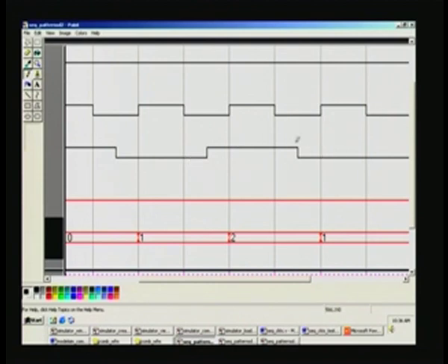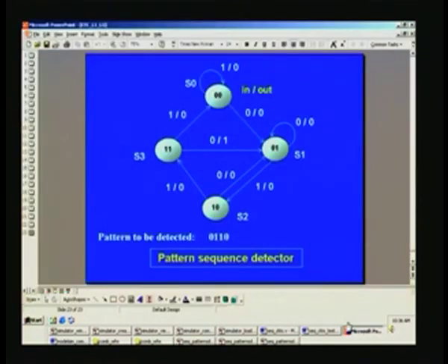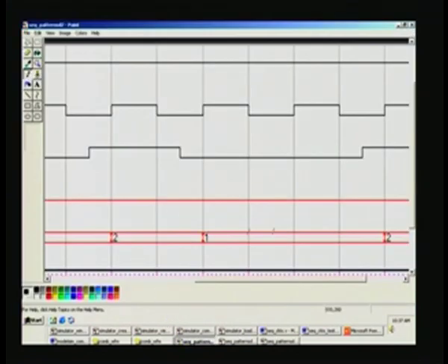So, naturally we will continue to remain in the same state, as per this. So long as it is 0, it was 0 there, and it went to state S1 and then continues to be in S1 so long as 0 is the input, and the corresponding outputs are all this here. What is indicated as out in the waveform is precisely this, and in is this. So we continue to be here in S1 state, that is here.